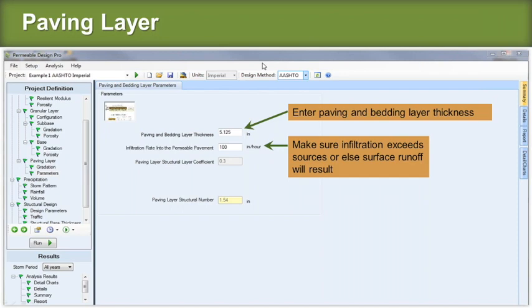So you can design this for something substantially less. And so usually we look at these and we say, yeah, it started out at 100 an hour or whatever, and we're going to design it for 10, for 6 inches an hour. 6 inches an hour is still a huge amount of permeability. But you have to be cognizant. I'm working with somebody in Texas now on a project for an alleyway where you've got tons of water coming from all the buildings around it, and the ratio of incoming to permeable surface is so huge. I can get the water to the pavement, but the pavement can't get it in at the end of the day. So this is where this comes into play.